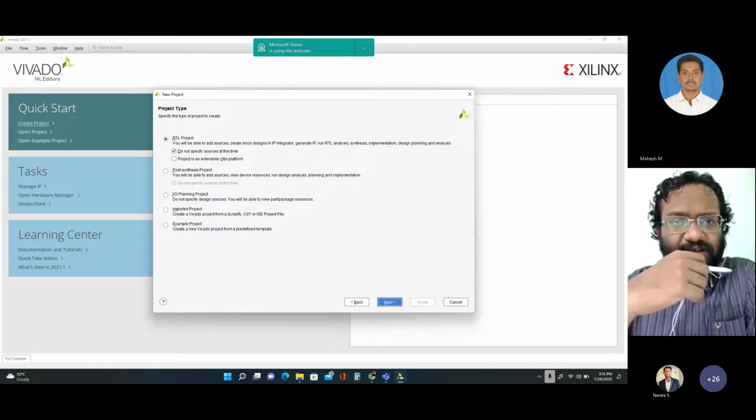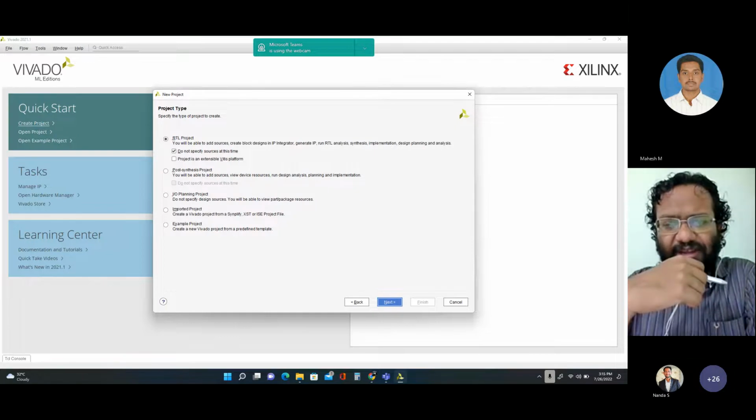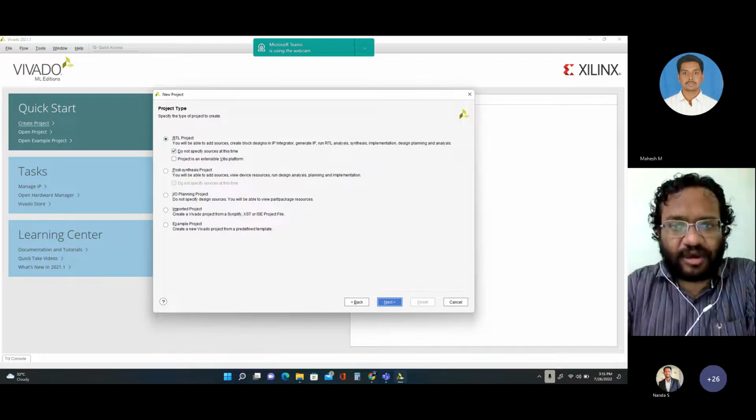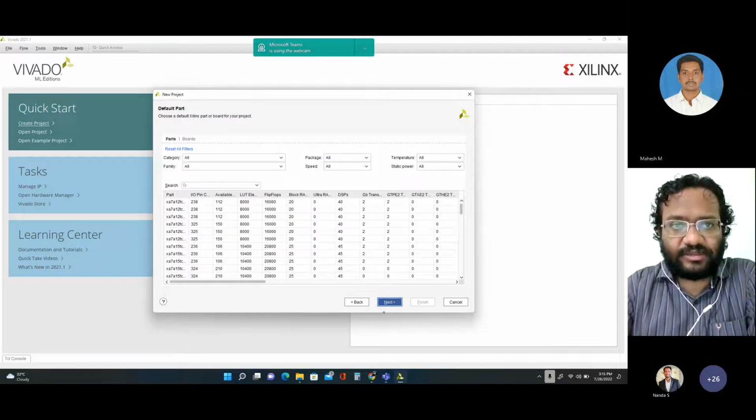And don't select the second box, that is the platform, which is mainly used for SoC design. So that we will check on, I think, the fifth day. So after RTL project, click next.